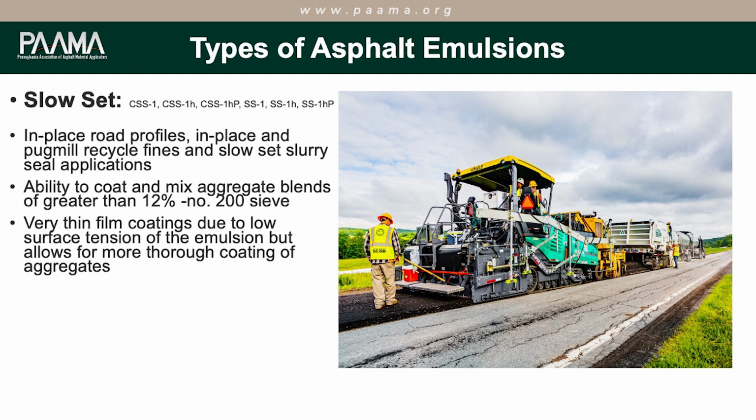So these slow sets are going to really help you with in-place train work. These grinders, they create a lot of dust. The slow set emulsions are going to sort of fight against all the surface area and the dust and still allow you to mix and pave.